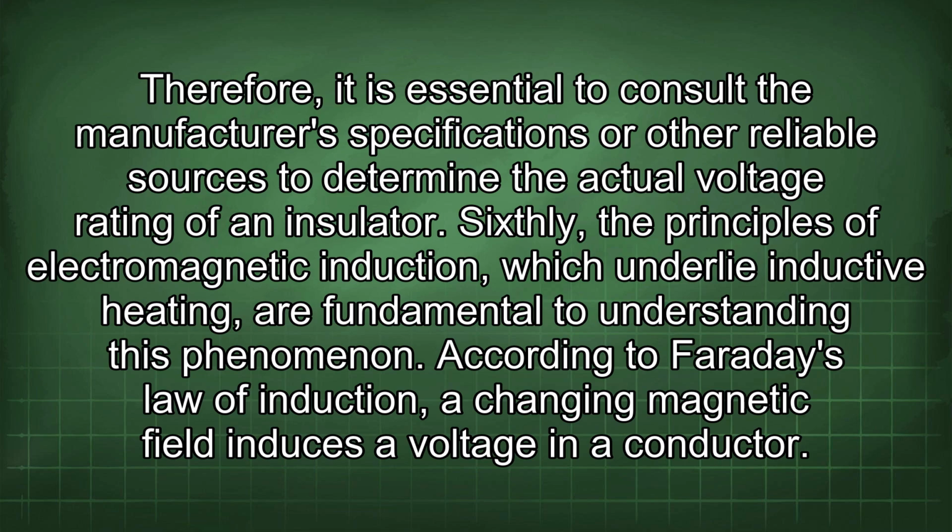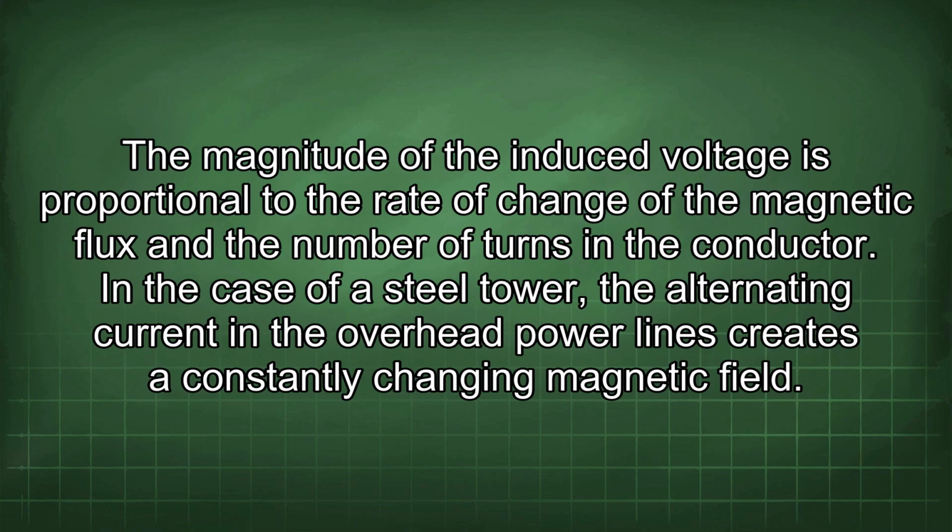Sixthly, the principles of electromagnetic induction, which underlie inductive heating, are fundamental to understanding this phenomenon. According to Faraday's law of induction, a changing magnetic field induces a voltage in a conductor. The magnitude of the induced voltage is proportional to the rate of change of the magnetic flux and the number of turns in the conductor.